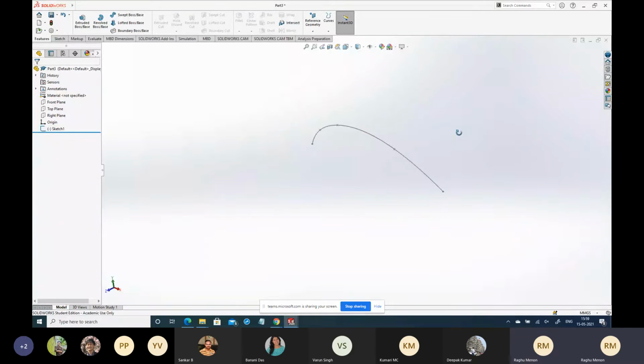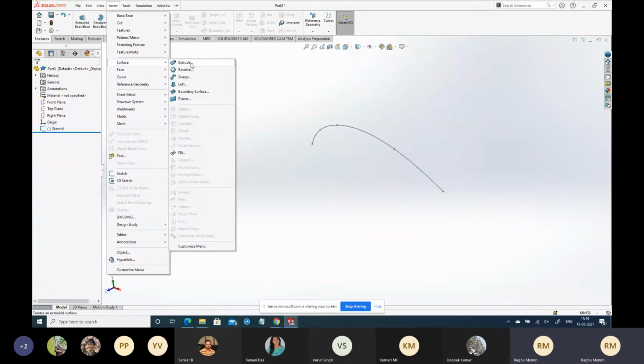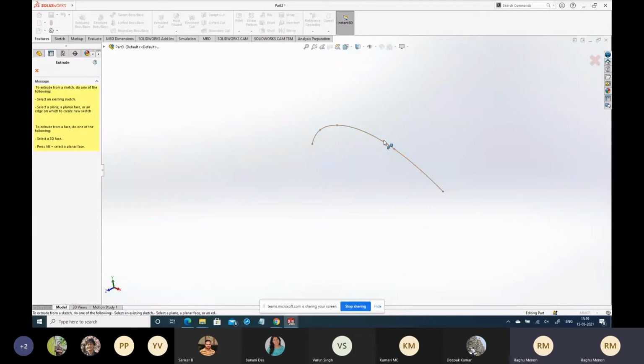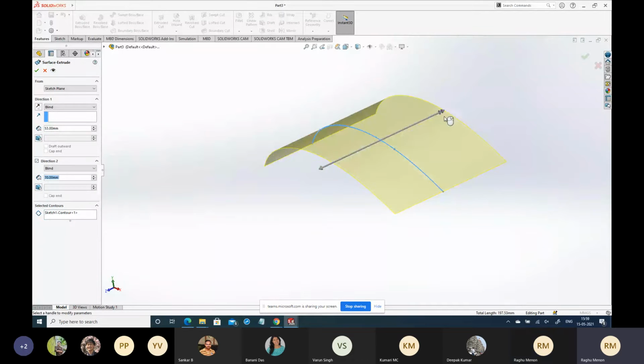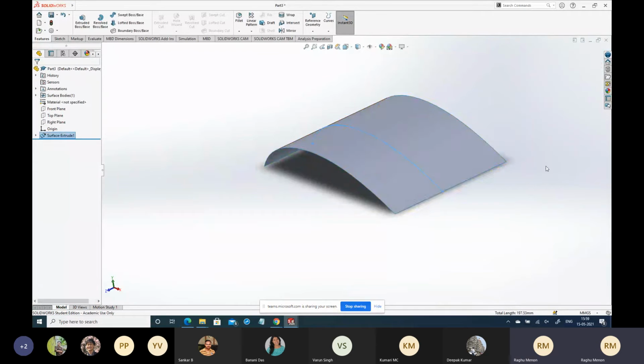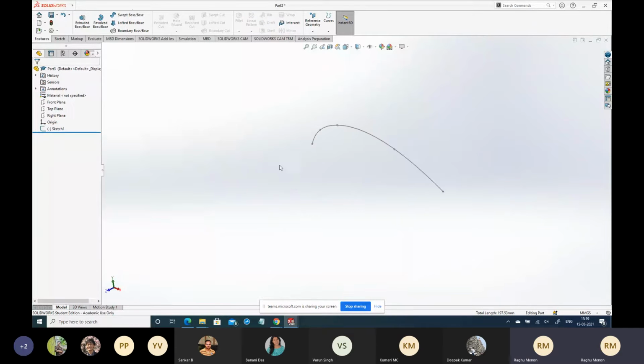Of course, now with just one curve, you can actually go to SolidWorks, insert surface, and say extrude, and pick this. You will create horizontal surfaces, right? And if I add a direction too, I can do a horizontal surface. So you can create these singly curved kind of things, not doubly curved. So this is not what we want, but I'm just trying to create this.